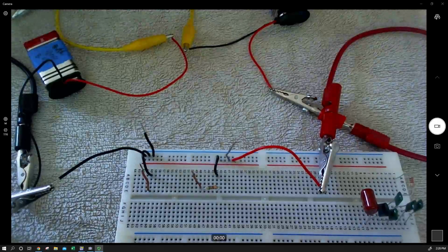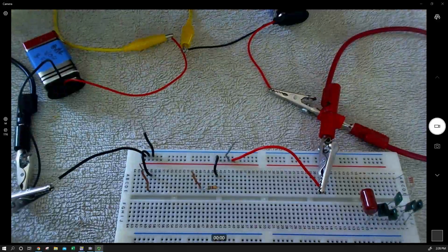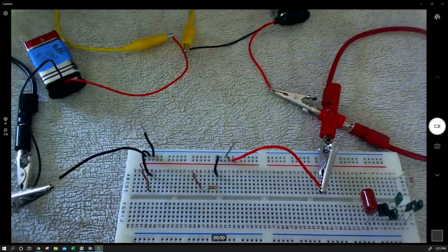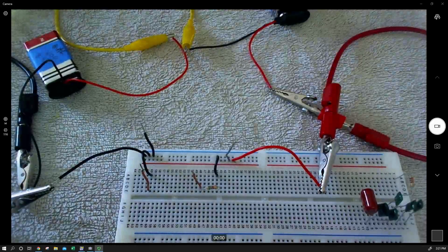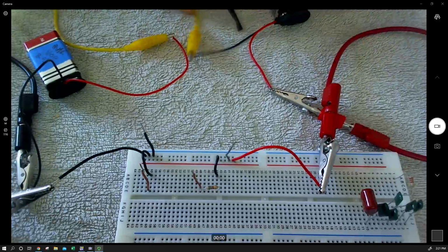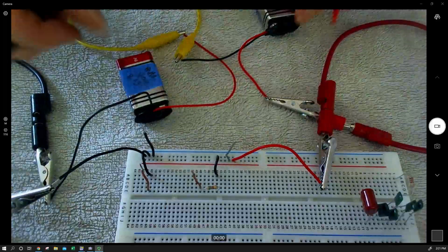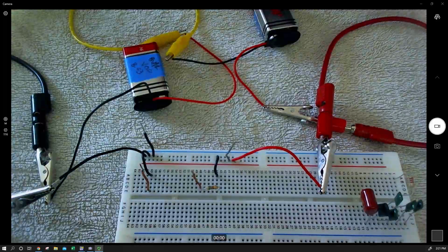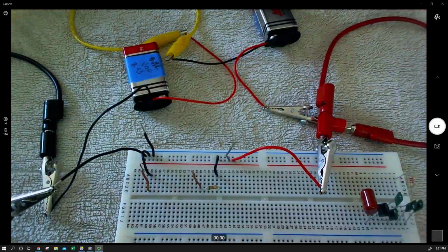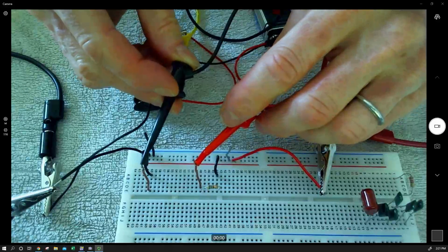So the last thing to check is, what does that do with my current? And will the circuit basically follow Ohm's law, or will it not deliver as much current as I expected because of that? Remember, we're dealing with a couple of sources that are somewhat depleted, and they have their own resistances. So how does that affect things compared to our fairly significant, back to our 5.6K load? So if I measure current,